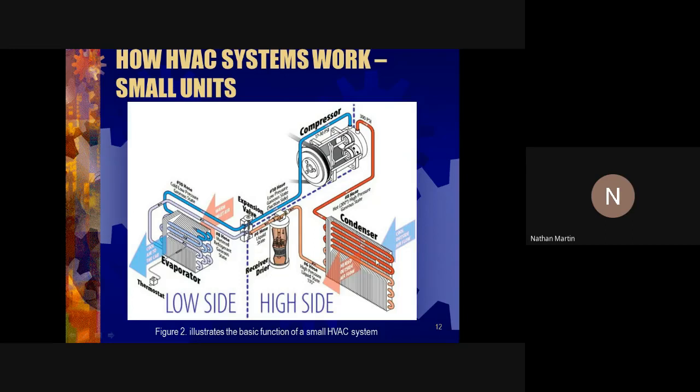The condenser would be where your radiator is, and then you will have your evaporator. Your compressor is going to be in your engine room again. In your engine room, your compressor is attached to your engine and it is turned via a belt. When you engage your AC, meaning put power to your AC, it engages the gear inside the compressor and starts to pump the refrigerant around the system.